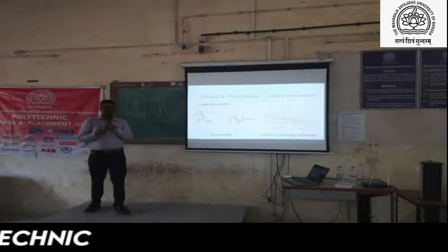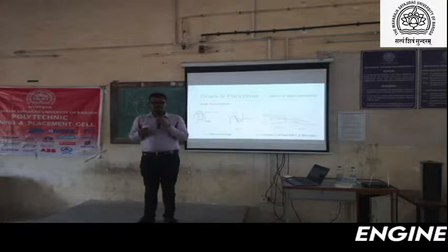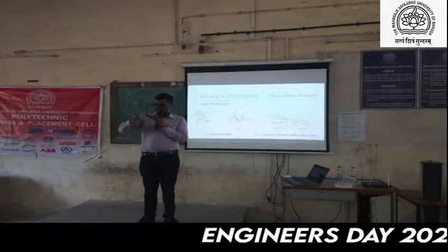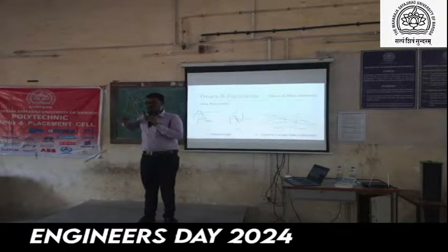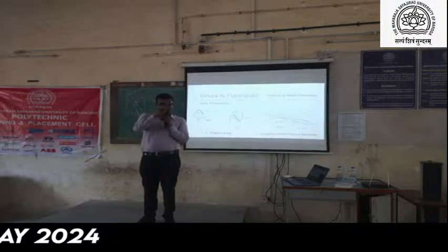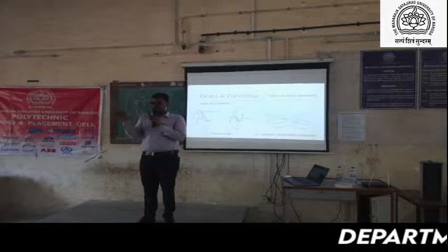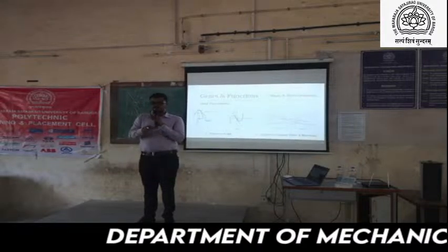See, parallel has no angle; the angle is zero. Helical has some helix angle. If you tilt it, the contact area can be increased. So comparing spur and helical gears, helical gears have much more load carrying capacity than spur gears.